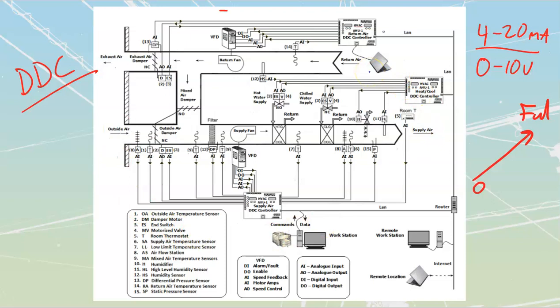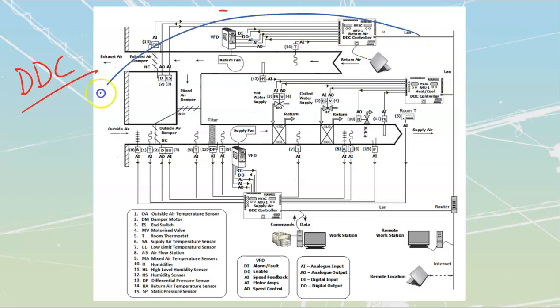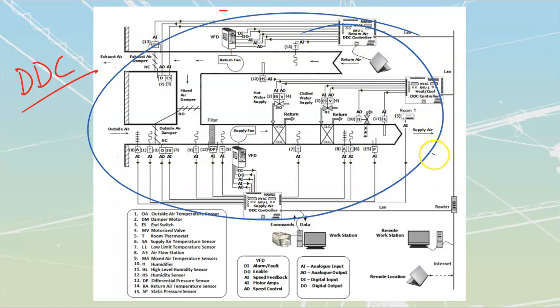A lot of our rooftop units, we talked about those at the very beginning of commercial HVAC, are going to have communication software built into them. Not the low-end, cheap, small ones for small commercial places, but a lot of our larger ones will have that. And so they've got all of this already built inside of it. And usually then it's just going to be a single Ethernet network connection out. So we'll bring power up to that thing. We will bring an Ethernet cable up to that thing as well. And we'll bring that Ethernet cable down to wherever the router is going to be from those rooftop units. It allows them, once again, to monitor all components inside there.